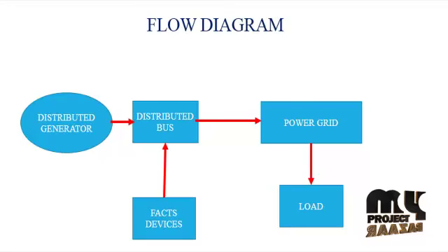Generally, the voltage control action of the SVC, that means static var compensator, can be explained through a simplified block representation of the SVC and the power system. The power system is modeled as an equivalent voltage source Vs behind an equivalent system impedance Xs as viewed from the SVC terminals.